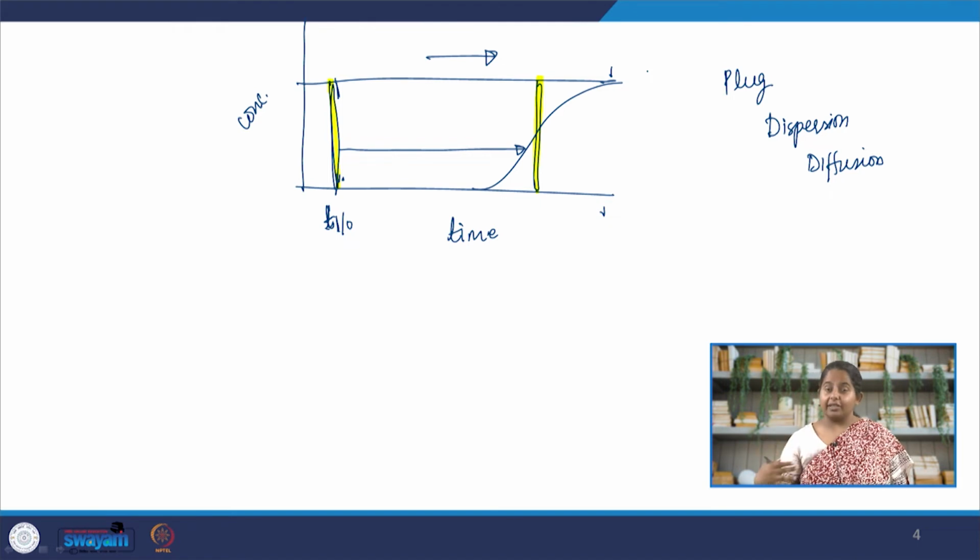Remember, in the z direction we are assuming it's already perfectly mixed. There is no diffusion happening there because the aquifer is not very big in the z direction. But here the diffusion is happening in the x and y directions. There's another feature of groundwater transport that we need to look into.